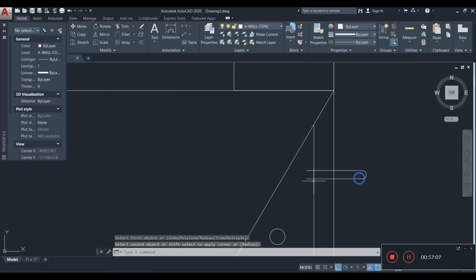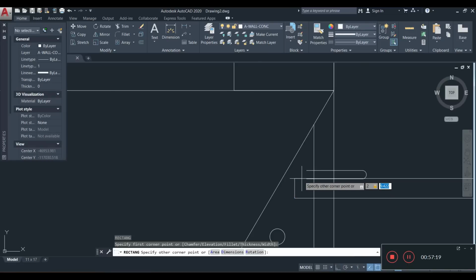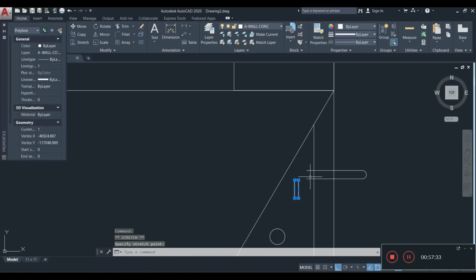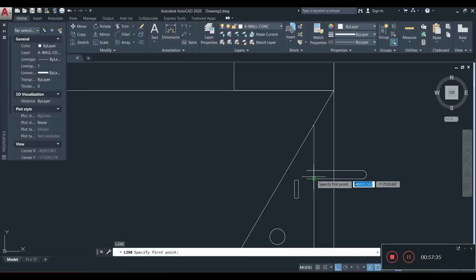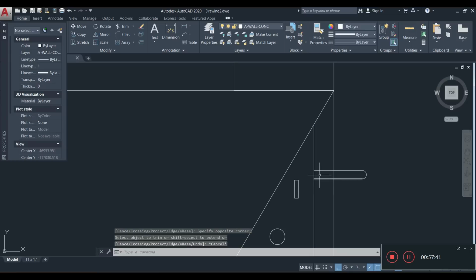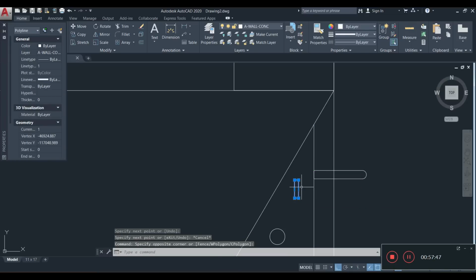Now this is like a nail, so let me just use a rectangle, REC, enter. The width of it is going to be 2, then tab key, the height of it is going to be, I don't know, 2, let's make it 4. Yeah, we can always adjust that up a bit. And let me just add a little line somewhere here, or trim away whatever is here. TR, enter, get rid of that. Let me add a little reference line on it somewhere there, and let's move this there.